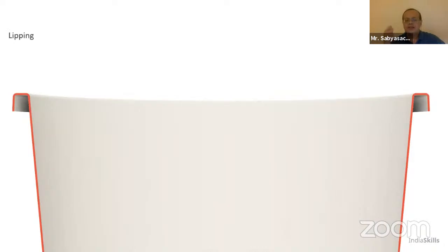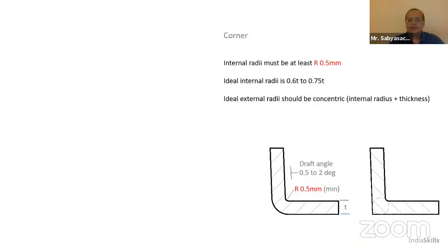Let's talk about stiffening a component. So if you look at your bucket, which you're fairly familiar with, if you notice on the top, you have a rim. And it is not just ending in the wall thickness. It's turned up once and then twice. What that lipping does is that the lipping strengthens the component. Have you ever tried cutting the top portion off? Then your bucket will not retain its geometry. So the lips are very important to retain geometry, not adding thickness. That's very important to understand, right?